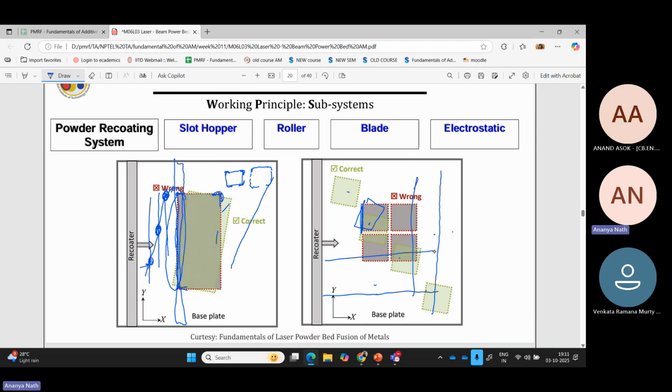So you see, if your recoater blade is coming and it gets ruptured because of the sharp edge, then the rest of the parts which are in this line can be damaged as well. So if you are optimizing your part, if you are printing a new powder, if you are optimizing for cube printing, it's always preferred to orient the part like this, say 4 parts, instead of this.